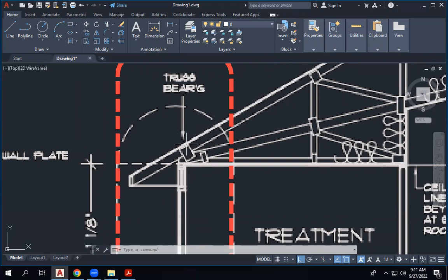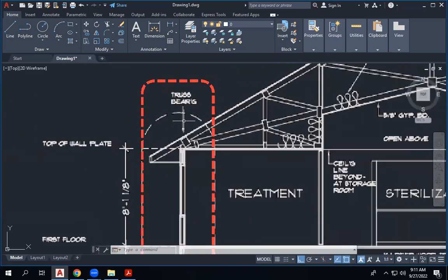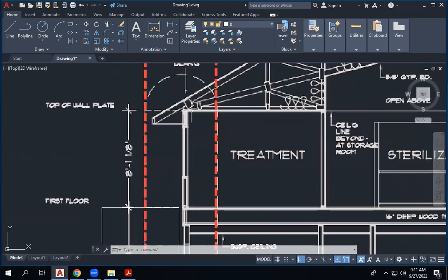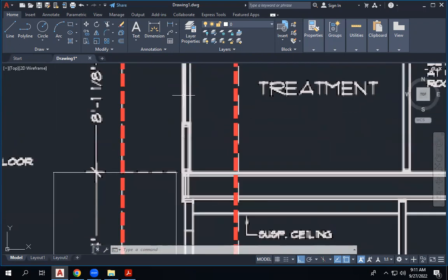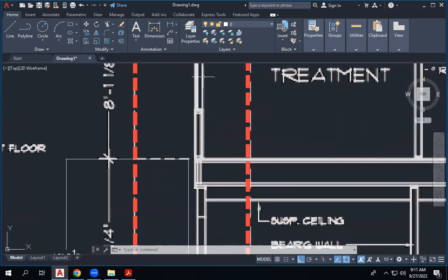We will make another line thickness of 0 for the dimensions, and we will have another layer at 0.1 for anything like a window or window projection. We will keep that one because there might be so many lines touching each other in the window. So we'll keep 0.1 for that one. So we need four: 0.35, 0.2, 0.1, and 0.